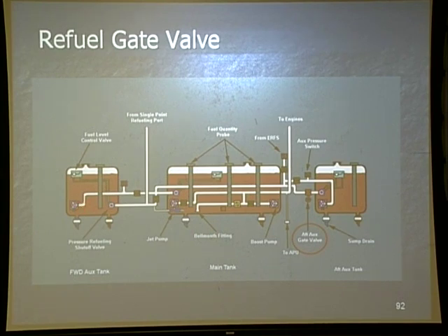And what I'm going to do is use the cursor for the computer. What you're looking at is the left side tanks. Everyone tracking? Fuel's going to come through here, and it's going to go into this forward aux tank. Good? Fuel's also going to go through this one-way check valve, and then it's going to fill up this main tank.